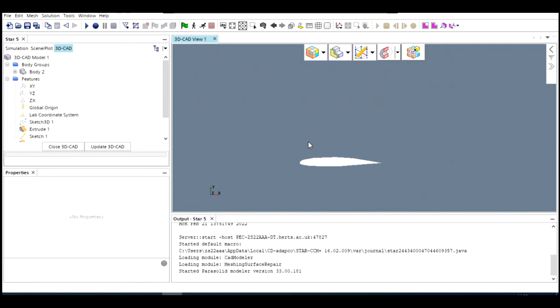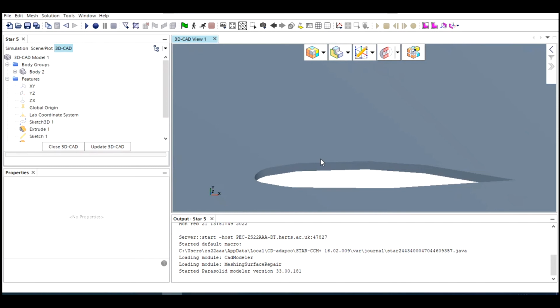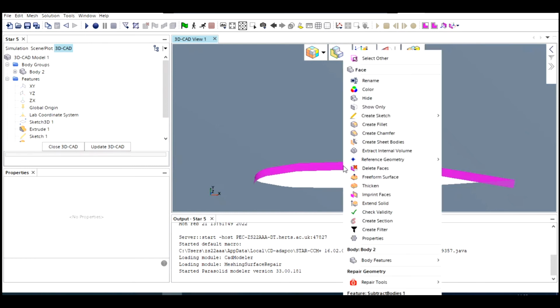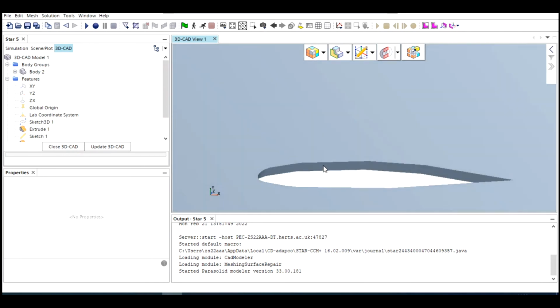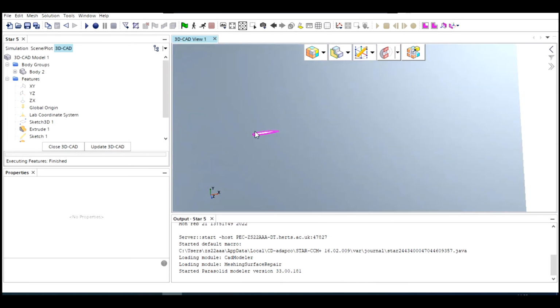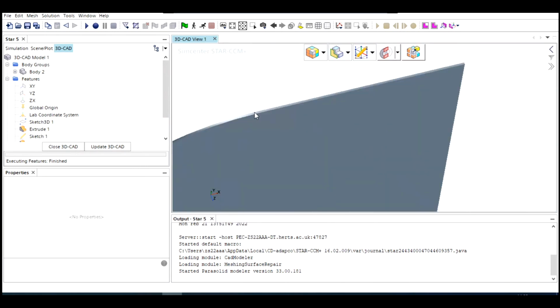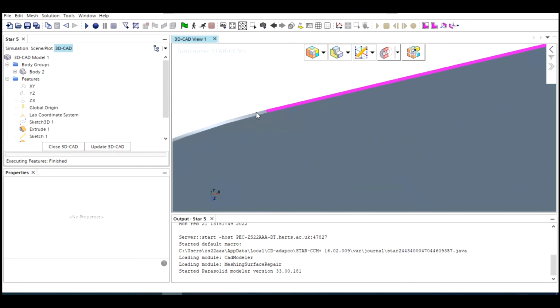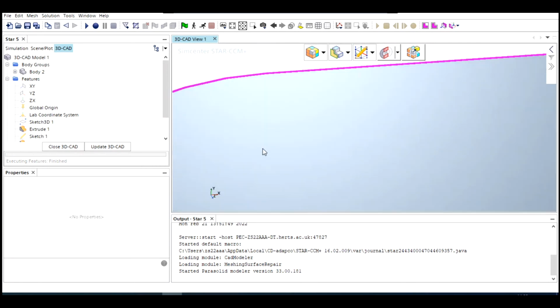And as usual, we need to name the surfaces. Then we can set up the boundary conditions. So let's right click both surfaces. We need to press Ctrl and rename them: aerofoil. Aerofoil. And here we have the inlet.